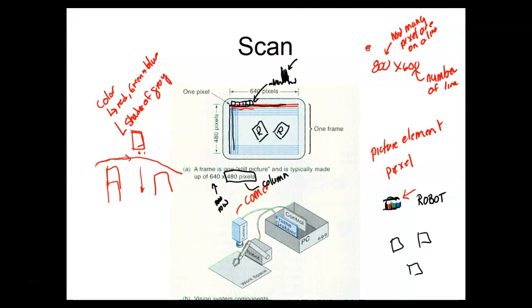A lot of things like that, we orient the way we want by having what we call jigs that the part moves into. It'll have to fall into the jig exactly the same way every time, and it orients it for us, and we clamp it down. I think on a lot of the cars, the frames have pinholes in them, and they move them until rods can come up into the pinholes. That's probably the most popular way, to mechanically orient it, because camera systems cost a lot of money, and somebody's got to be able to program these things.